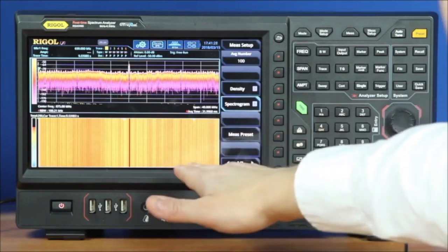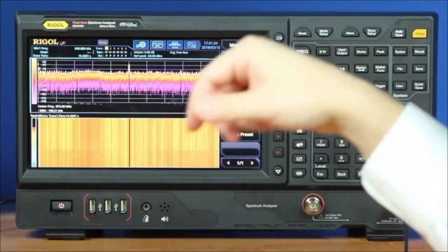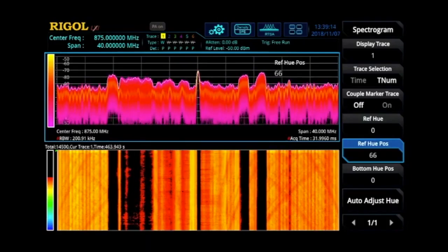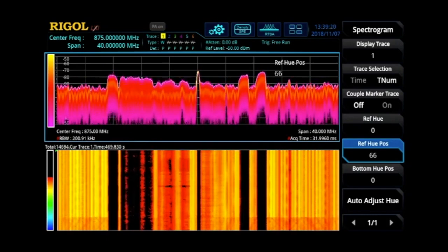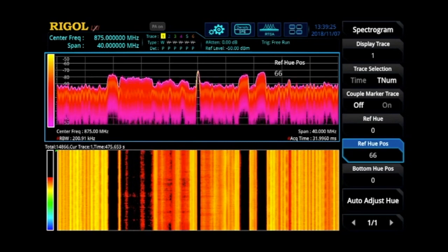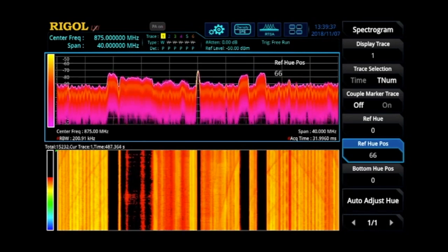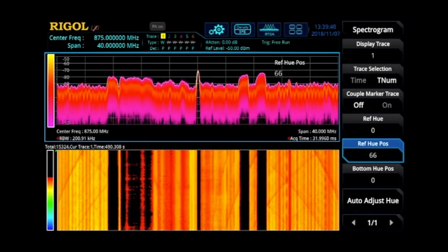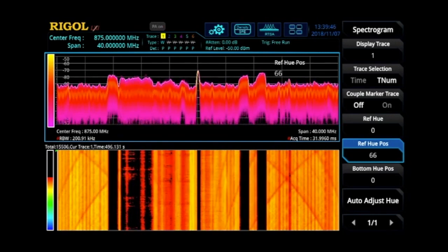We can see some subtle effects here as this chip that we're focused on really has a reset and then has some frequencies that move around in this span that are frustrating us. We take a closer look, we can see right there a reset occurs and the power drops across this whole spectrum. Now over the next 30 seconds it builds again and resets, and this is a continuing, renewing kind of cycle. If that was annoying us from a pre-compliance standpoint or from a functional standpoint, we could use this kind of real-time test with super accurate RF measurements to isolate the ultimate cause of that, what's causing that dithering frequency and that power building, and do something about it.